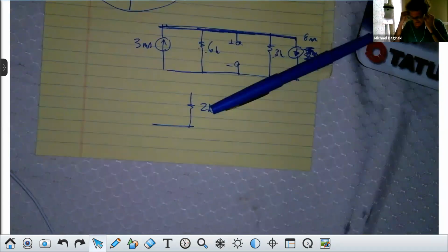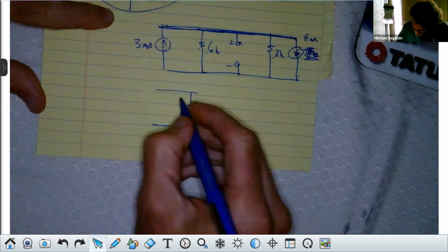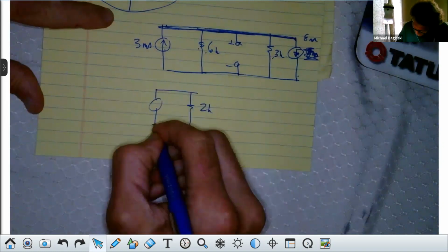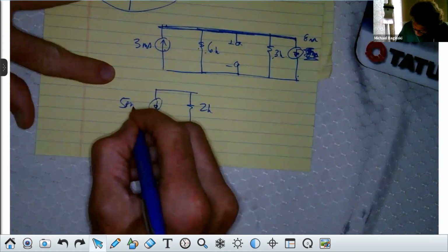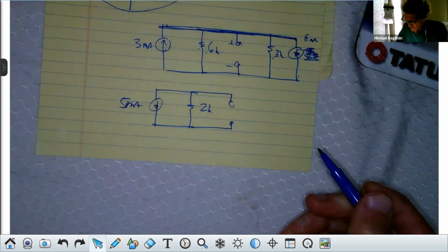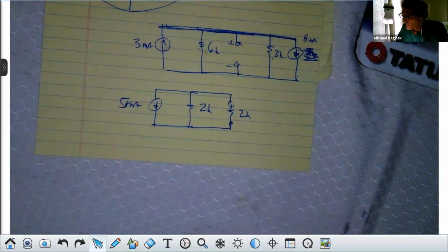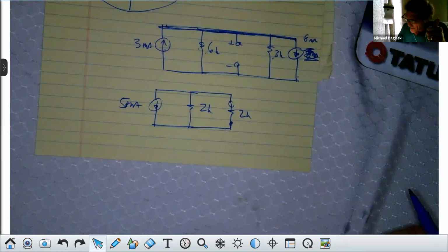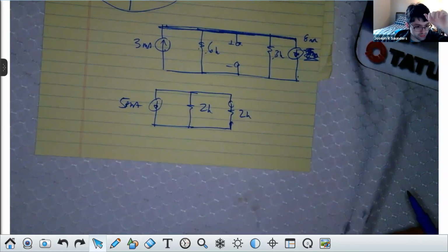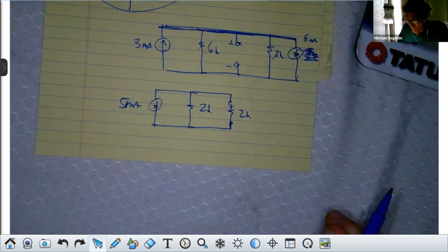All right. Okay, so I got 2K there, and I have minus 5, you can do it this way. I just put 5 milliamps going down, right? Y'all see that, right? And now what can I do? Now that resistor 2K I took off, I'm going to put here. Y'all follow me? I mean, this is perfectly legitimate what I'm doing, and it's easy. That way we don't have any matrix math, right? We just eliminate all the matrix math by simple transforms.